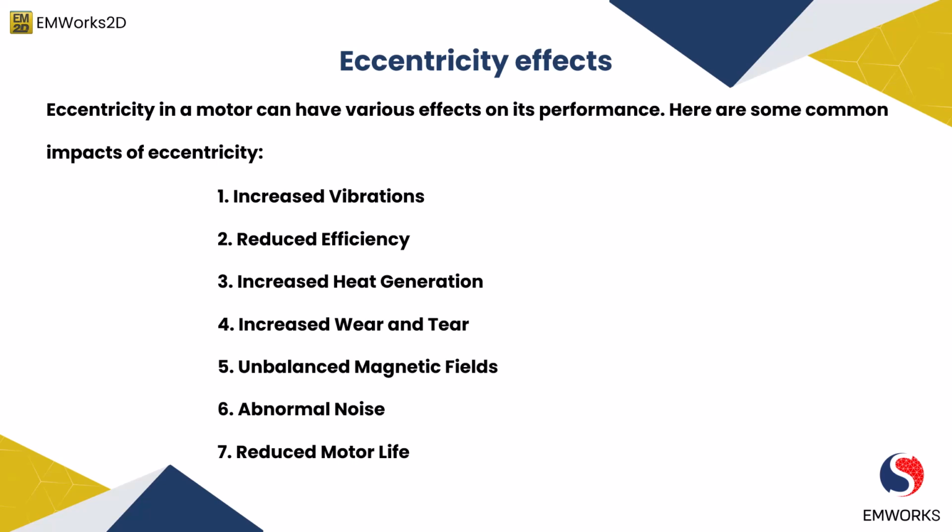We could also see a reduction in efficiency. Eccentricity disrupts the normal alignment between the rotor and stator, resulting in increased friction and losses. This can reduce the motor's efficiency as more energy is wasted in overcoming the additional forces generated by the eccentricity.